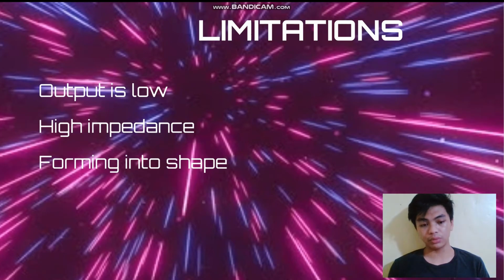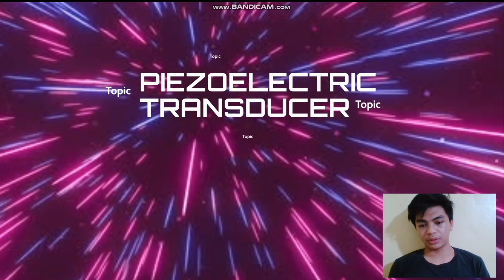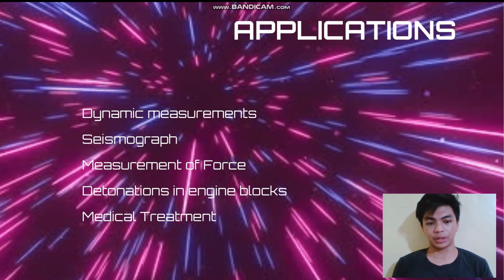The last one would be forming into shape. It is very difficult to give the desired shape to the crystals with sufficient strength. After the limitations, let's move on to the applications. The first one is dynamic measurements. Piezoelectric crystals are primarily used for measurement of quantities like surface roughness, and also in accelerometers and vibration pickups.